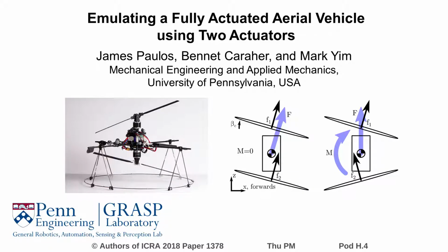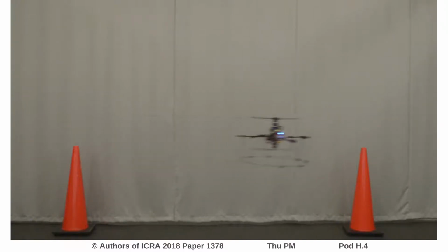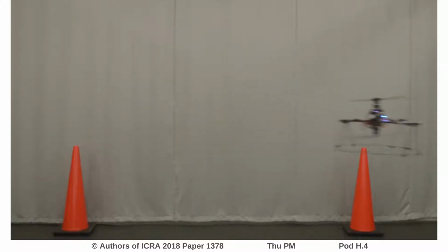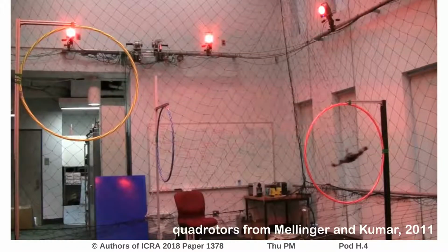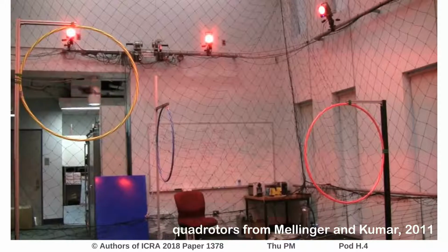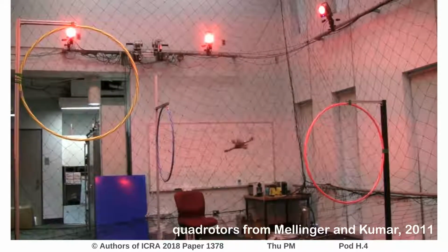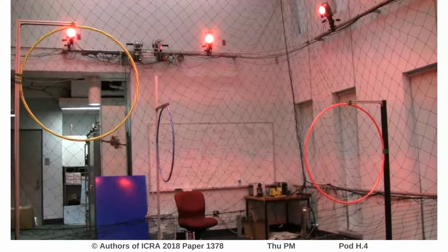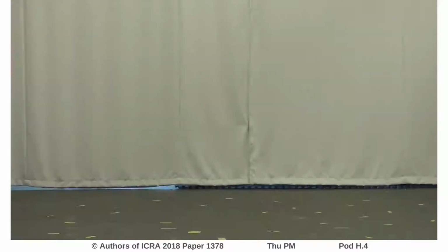This work introduces an unusual coaxial helicopter, which requires only 2 actuators total to independently control all 6 degrees of freedom in flight. The swooping pitch and roll of a conventional quadrotor is a fundamental requirement of its underactuated dynamics. It must roll and pitch its body in order to point the thrust vector in different directions and maneuver through space.